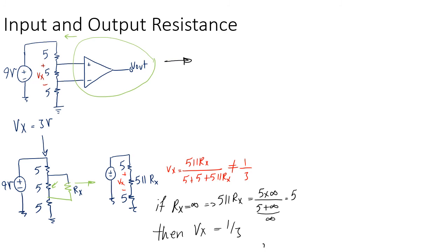So this tells me that if I want to sense any voltage and amplify it, because it's a voltage dependent voltage source, right? Remember, this op amp was a voltage dependent voltage source. So I had a Vp and a Vn and a V out here, and I was saying that V out is equal to A times (Vp minus Vn), right? So basically I'm sensing the voltage difference between Vp and Vn, and then I'm amplifying it and generating this V out, right? When I'm sensing something, it's kind of like measuring something. I'm measuring the voltage across something, and then I want to amplify it.